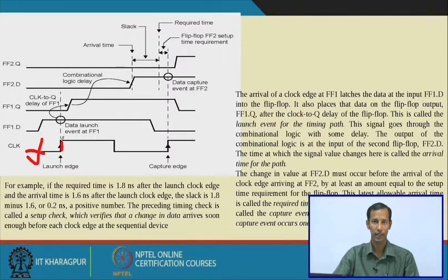Whenever we get the first positive edge of the clock, it checks the value of the data. Here the value of the data is 1, so after some time flip-flop 1's Q will go to the 1 state.